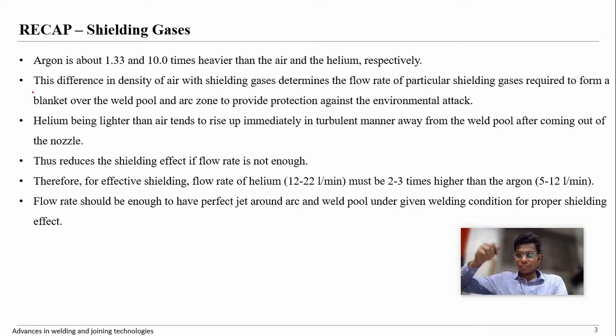So during welding, if I am using argon as an inert gas, its density is more than the surrounding atmosphere, the air. So the argon shielding gas will stay near the weld pool only, and it won't go away from the weld pool easily because the density of argon is more.